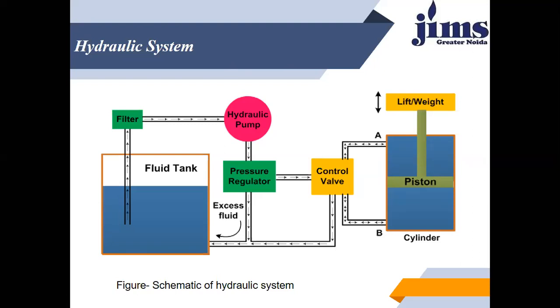The intake of this hydraulic pump is connected to what? This fluid tank, where the fluid has been stored, or you can say the fluid reservoir, right? And I already explained the control valves. So three control valves you must keep in mind: pressure control valves, flow control valves, and direction control valves. Pressure control valves control the liquid pressure, flow control valves control the liquid flow rate, and direction control valves control the direction of flow of the liquid.